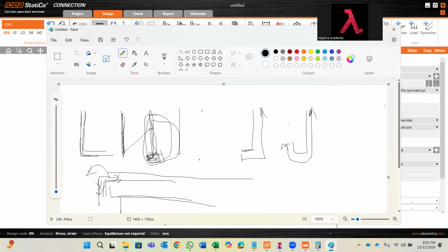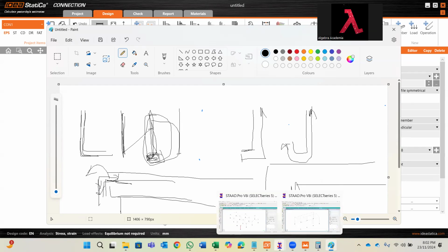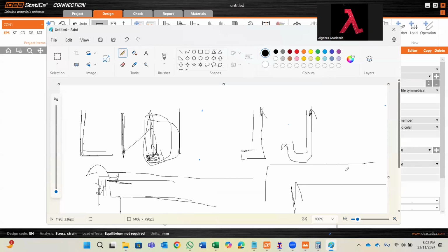When you want to use the straight bar, say for example my shear wall is huge, then I don't need to take the top bar and bend it. Say my shear wall is 2 meters. Then the top bar is, say, 25 millimeter diameter. Maybe you're talking about 50 times of 25 millimeter, right? This is your development length, in general.